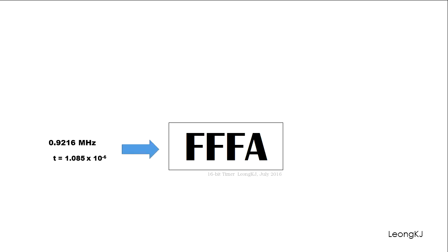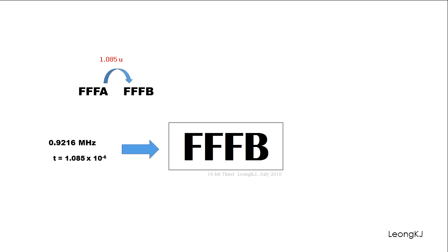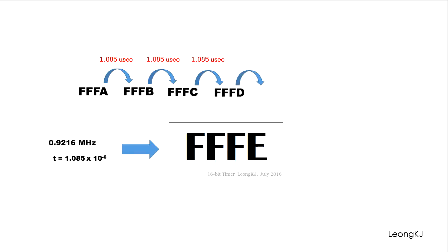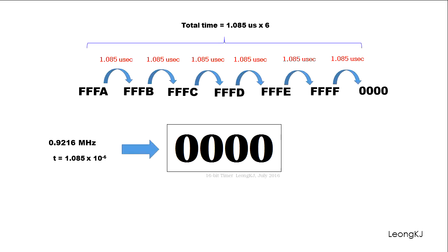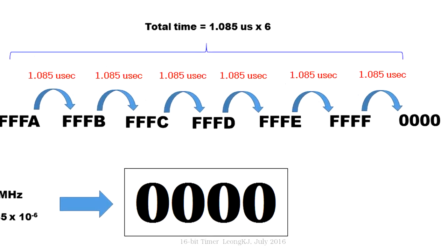Let's set our timer to FFFA. How much time does it take the timer to reach overflow? It took the timer 6.51 microseconds to reach overflow.